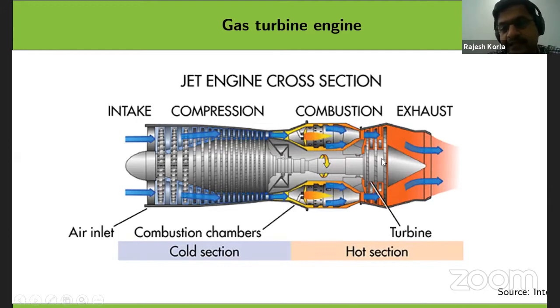Here the blades experience around 1400 degrees centigrade actually, but the actual blade material can withstand only 1100 degrees centigrade. So on the top, there will be a bond coat and thermal barrier coatings, and then also cooling of the blades and all those things will happen. Finally, it can withstand 1400 degrees centigrade. But the point is here, the temperatures are extremely high. At the same time, it has to withstand the corrosive environment of the combustion gases also. So here, high temperature strength is important, creep is important, along with good resistance to oxidation and other things.